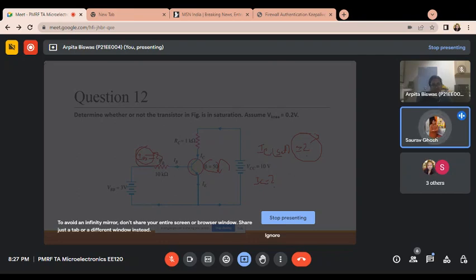But the IC sat is 10 milliamperes. No, a little bit less than 10 milliamps. IB is 0.8 milliamps, madam. 0.8 milliamps, how did you calculate it? You have to take the circuit, the loop. So tell me, what is the equation?